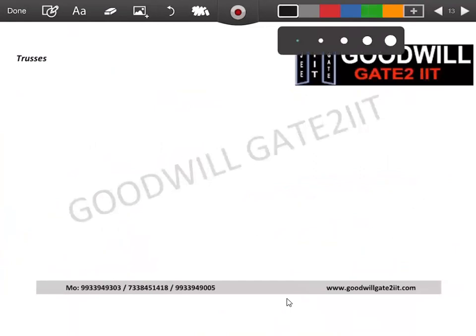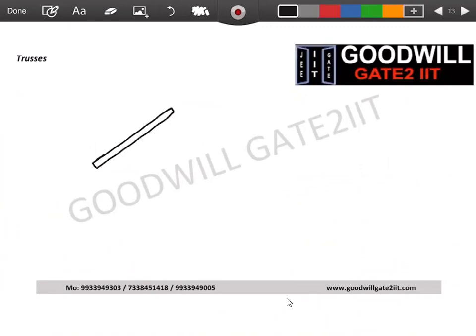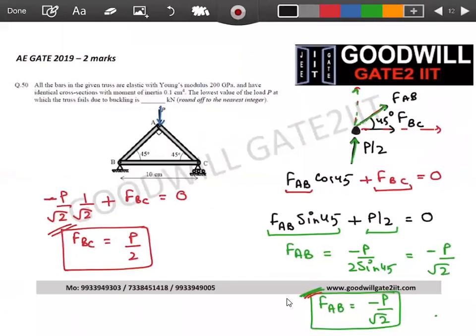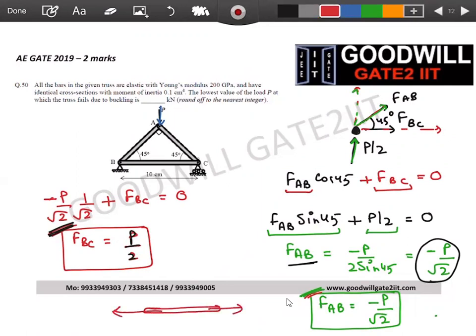So what you understood now is that there is a truss member, which you name it as AB. And this truss member, if you people see, AB is experiencing minus P by 2. What is this minus? Compressive load. But if you go to BC, it is experiencing plus P by 2, right? Means BC, if you people agree, is a member which is being pulled outside. This will never buckle, right? Problem is buckling means compressive loads.